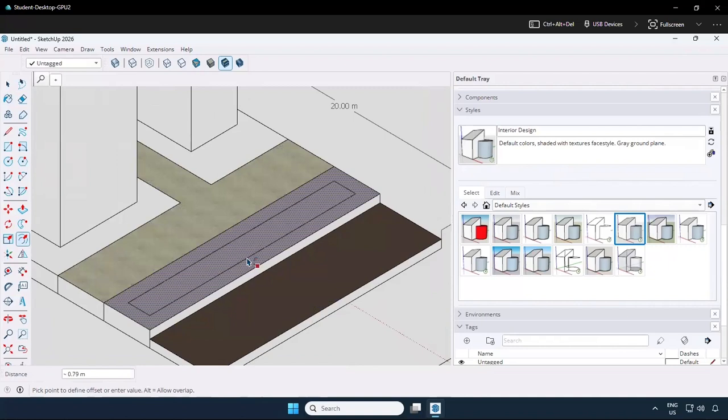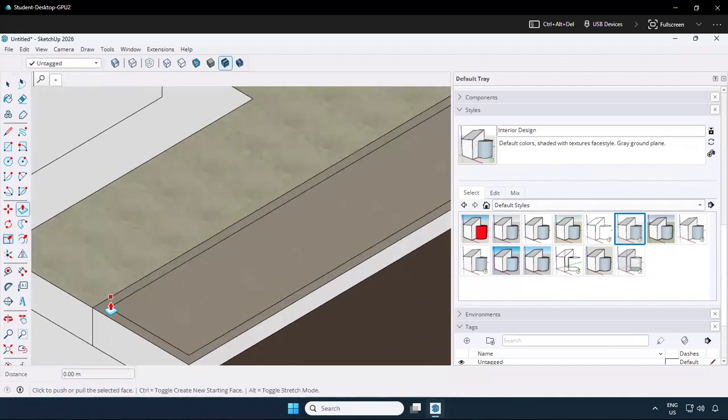So we left click once using that command once you open that. And you notice that these lines offset from that one edge. We can give it a particular dimension. So let's say it's 0.25, and that makes a line offset to that one. And we can continue to push and pull that one.